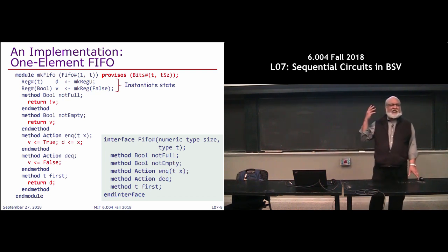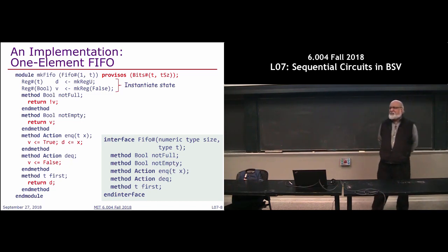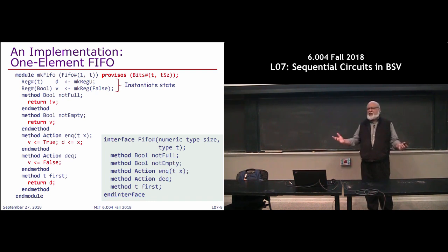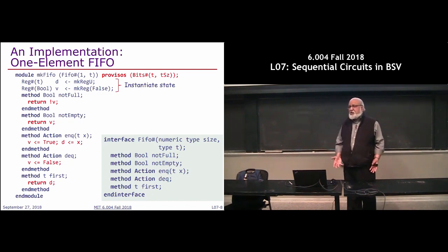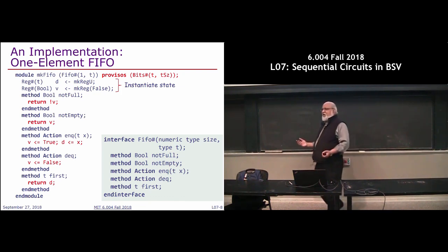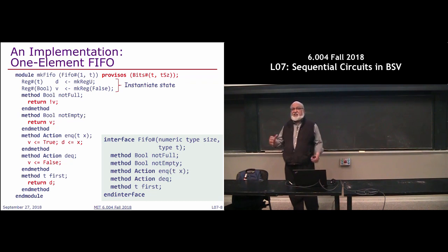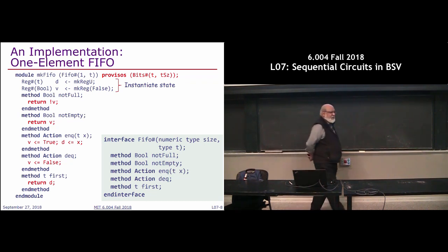The way you write it in BlueSpec is saying the type T must be something that is represented in size T as Z. So this is another free variable. You don't know how big it is. All you are saying is, please don't give me a T which I don't know how to represent in bits. You won't have to worry about all that because it will be done through pack, unpack, etc. The only assertion here is, if you're going to be storing some quantity, it must be bitifiable. It must have a representation in bits.